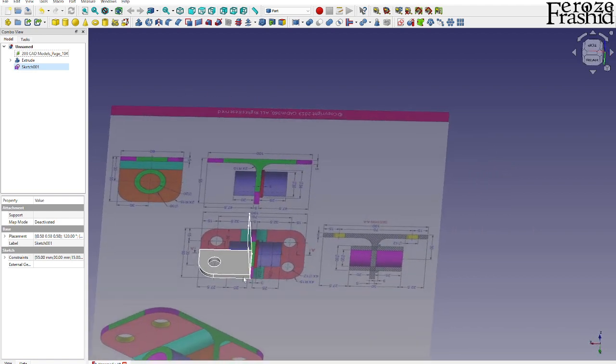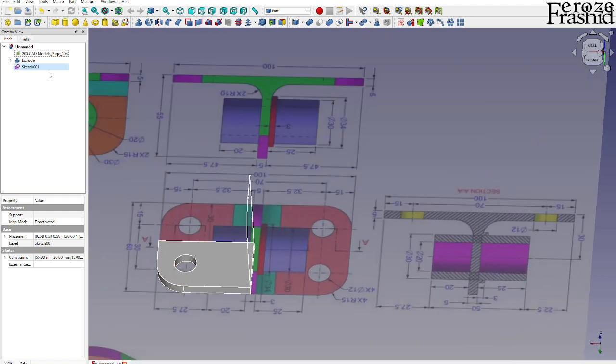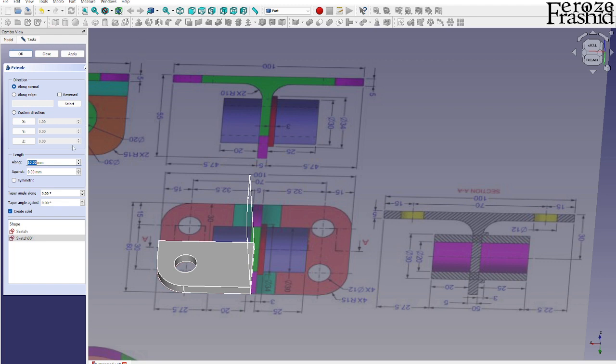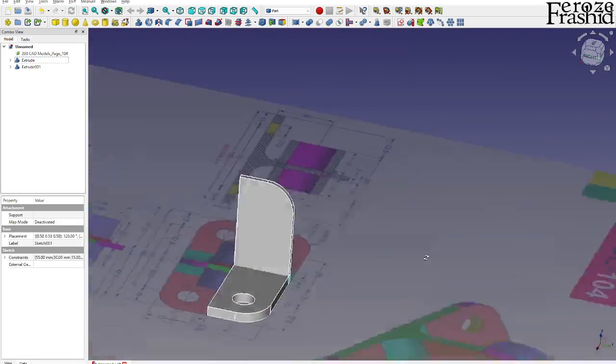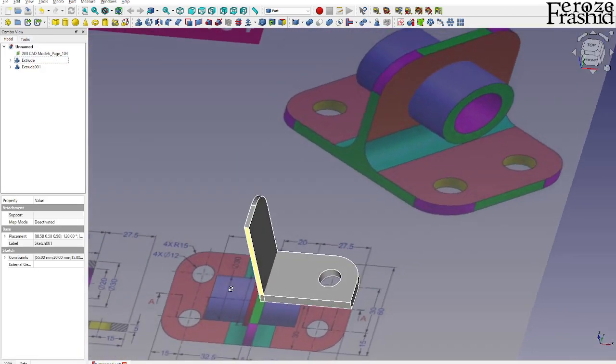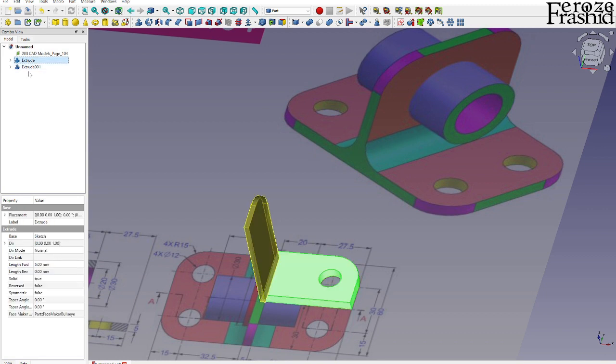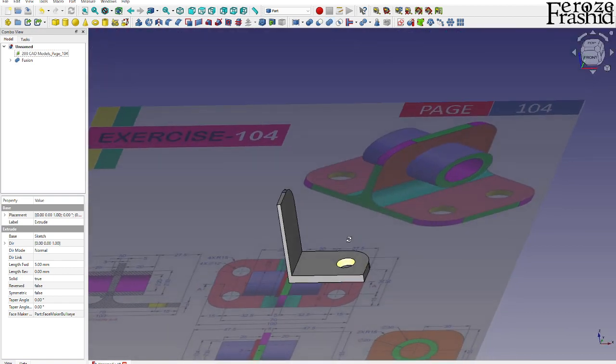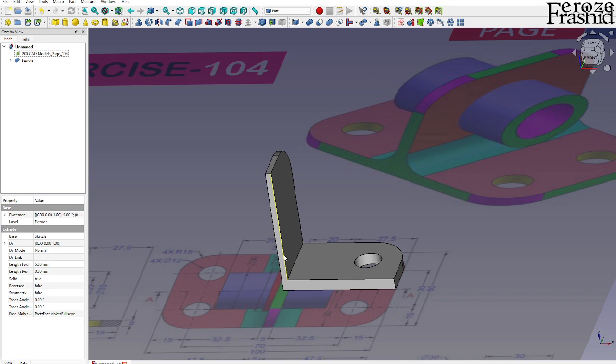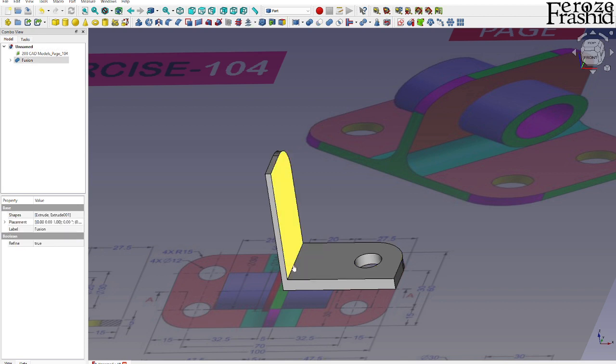So now we are halfway in the object, and I want to build the wall to 2.5 thickness, let's say, going to the right direction. Happy about it. Let's go ahead and union them. At this stage we must unionize this, otherwise we can't do the next step, which is filleting this corner. I want to fillet the corner if I can select this line.